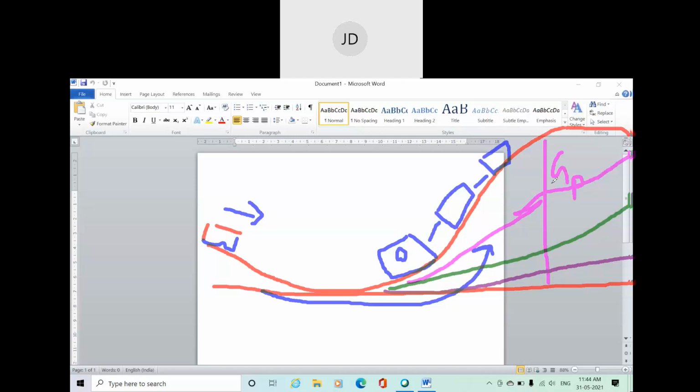In the pusher gradient, we need an additional locomotive to attach with the train to push. If the provision of ruling gradient is costly, then at that point along the high gradient, an extra locomotive can be used to negotiate the gradient of higher value.